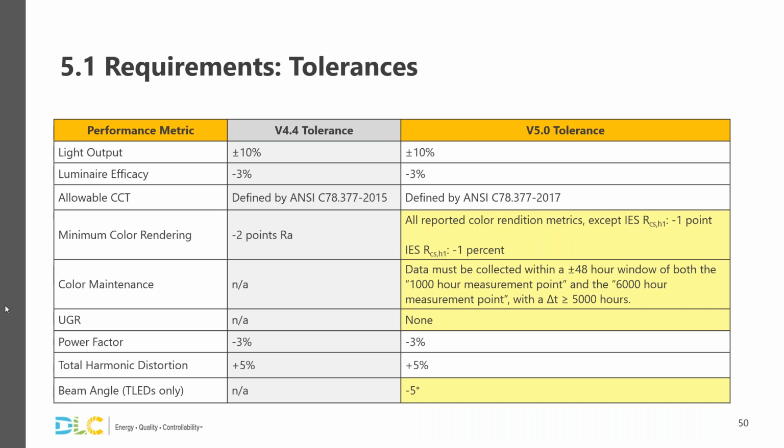Okay, thank you. Do you see the next question there, Yao? Yes. Is the 5 degree by 22.5 degree a minimum requirement, meaning you can measure and report more granular angular measurements? So I think this is referring to the luminance distribution data or the candela array in the IES file, and the answer is yes.